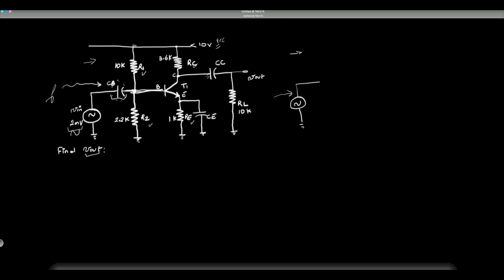So is this one. This allows us to connect two stages. So that means it allows this source to connect to the amplifier and the amplifier to connect to the load. But we don't want either of these two to have an effect in AC on the signal as it's processed through the circuit. So in other words, we want this ZC and this ZC to be almost considered zero.